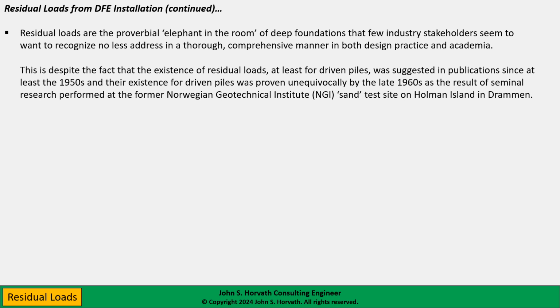So residual loads are the elephant in the room, despite the fact that the existence of residual loads, at least for driven piles, was suggested in publications since at least the 1950s. And their existence for driven piles was proven in the late 1960s by some very seminal research performed at the former Norwegian Geotechnical Institute sand site on Holmen Island in Drammen, Norway. And I'm going to talk about the NGI tests a little bit later in this presentation.